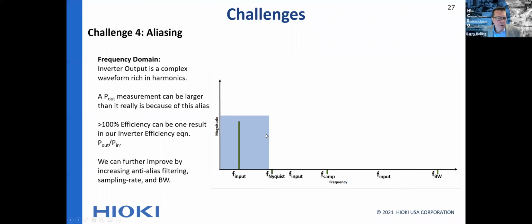And also today's power analyzers, the modern power analyzers, will have some anti-aliasing after the A to D, which includes oversampling and additional filtering. And certainly Hioki's doing that now. So anyway, here's a real world filter.